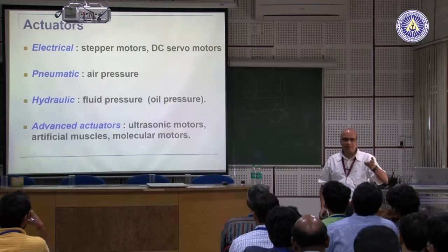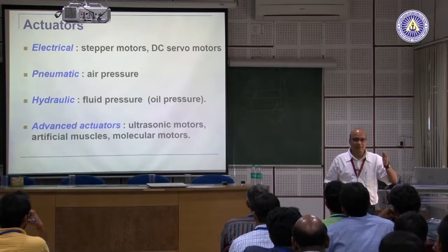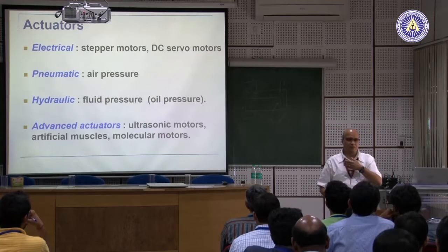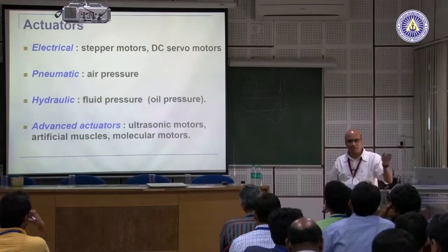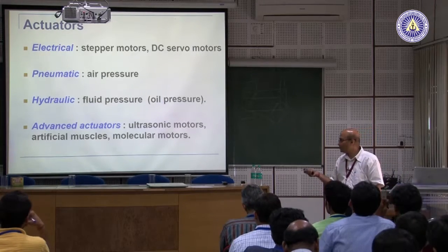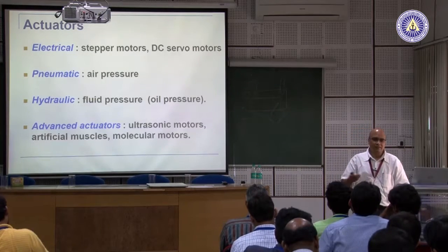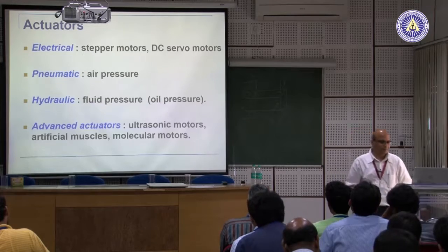So what will happen is either the gear will break or this part will break, because high gear ratios are not back drivable. Whereas if it is pneumatic, it will just move back. So it is safe. That is why pneumatic grippers are used from a safety point of view. Suppose there is a mistake and it hits something, then it will just move back, and that is it.